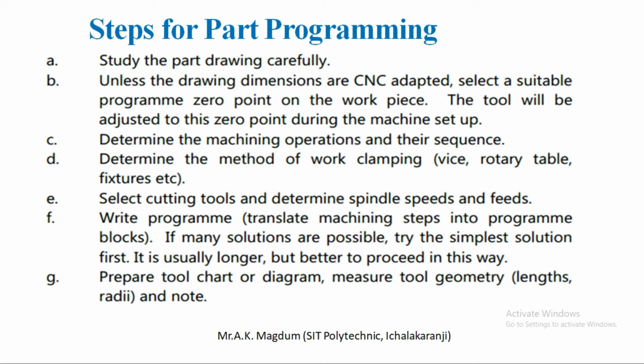Next one is to write the program. Write program means what? In this we translate machining steps into program blocks. What instruction do you want to feed to that machine? What type of movements are required? What type of motions are required? All those instructions which are fed to the machine in the form of programming codes, that set of instructions is nothing but a part program.